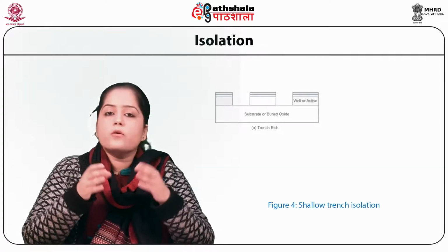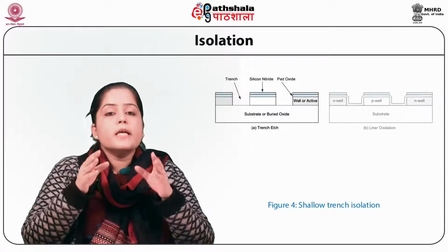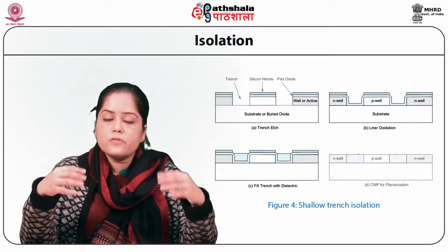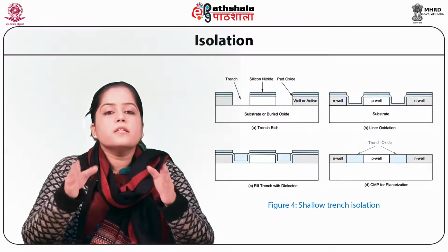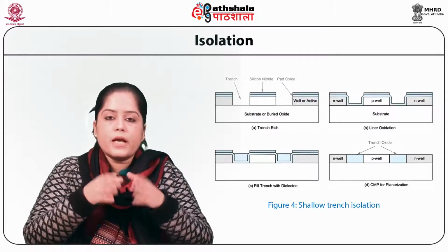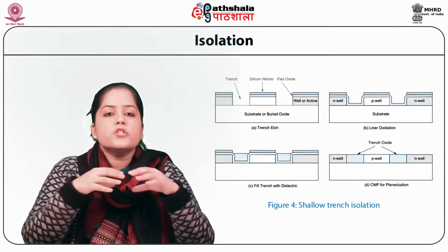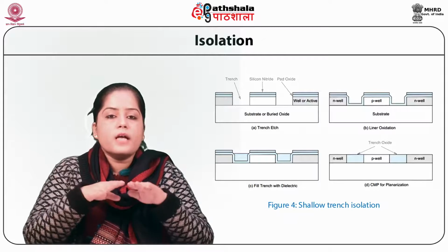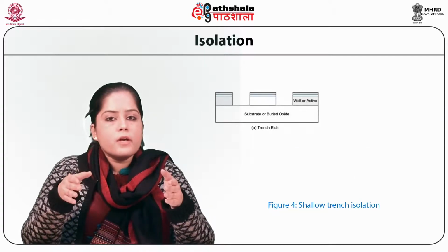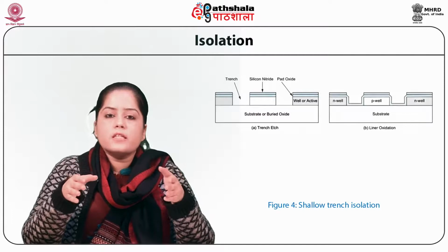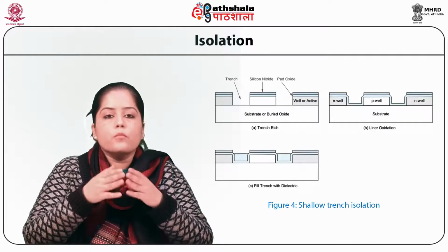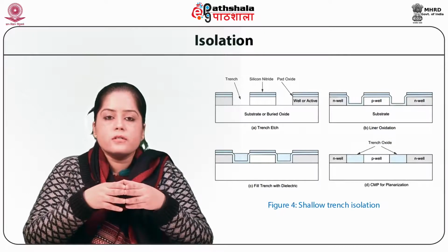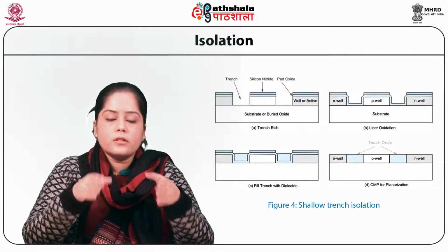Let us discuss isolation. Individual devices in a CMOS process need to be isolated from one another so that they do not have unexpected interactions. In particular, channels should only be inverted beneath the transistor gates over the active area. Wires running elsewhere shouldn't create parasitic MOS channels. Moreover, the source-drain diffusions of unrelated transistors should not interfere with each other.